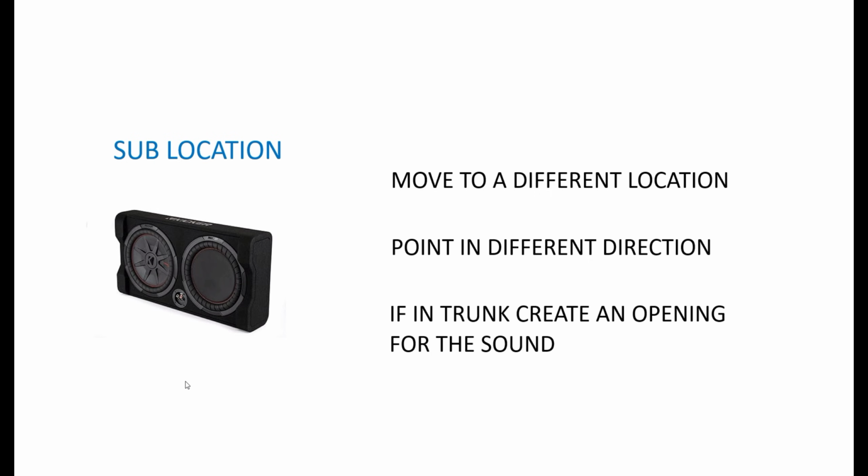This sort of talks to this thing of what we call coupling. So if you're in an SUV or a hatchback where the cargo area and the cabin space is one area, then there's a high degree of coupling, right? Because they're basically one air mass. But if you have your subs in an enclosed trunk, then you have low coupling because they're two separate air areas. So often if you create an opening, so open the ski hatch or drop the rear seats, the bass response will change at the listening position for you.